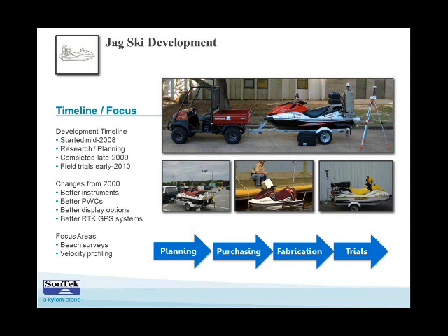So we're doing surveying not only for monitoring, but also to set up and establish a hydrodynamic model of tides, waves, and sediment transport that can be used to manage the site into the future. So this is when we started doing the project using River Surveyor and River Surveyor Live, we would take all the information, take all the profile data, and then clean it, distill it a little bit, and then interpolate, make our own maps out of it with some different software.